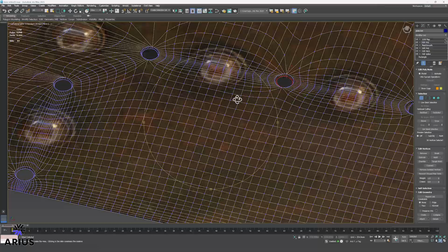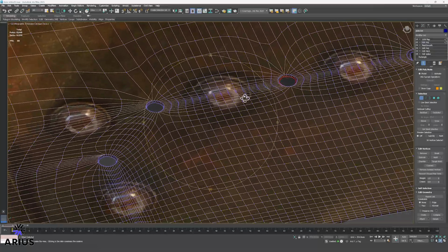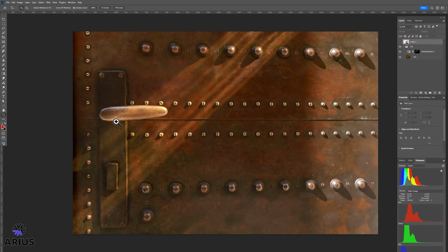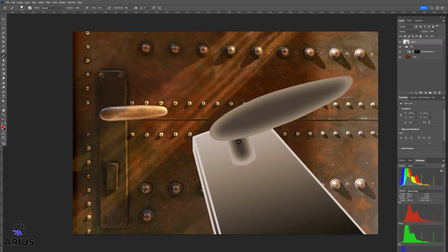At this point, let's consider what we're creating in the final output. A 2D image that represents a 2.5D version of a 3D object. We can't print undercuts, so right away we need to keep in mind that it's not appropriate to use fully three-dimensional representations of each object we know and understand. We can't see the axle of the door handle. Logically we know it's there, but there's no point in modeling it, and there's no point in making the handle fully round either.